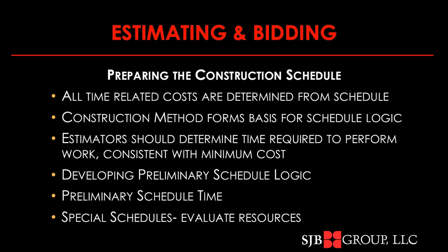So, preparing the construction schedule. All time-related costs are to be determined in accordance with the schedule. The construction method that you've selected in our previous section is going to form the basis for your schedule logic, how the various parts of the work come together in sequence. Your estimating team should determine the time required to perform the work consistent with the minimum cost.